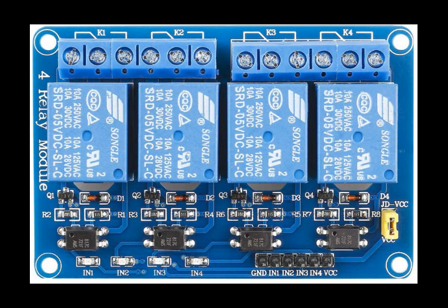Turnouts require 2 additional components. The first is a 4-channel optocoupler relay. The optocoupler separates the 5-volt section at the bottom of the image that is driven by the Nano from the potentially high voltage going through the screw terminals at the top. Channel 1 controls frog polarity. Channel 3 controls communications to the previous Nano, and channel 4 communications to the next Nano.